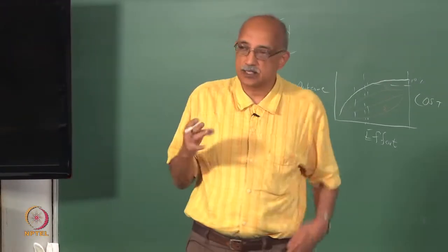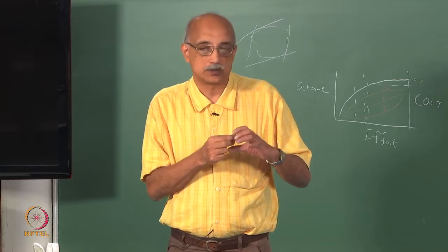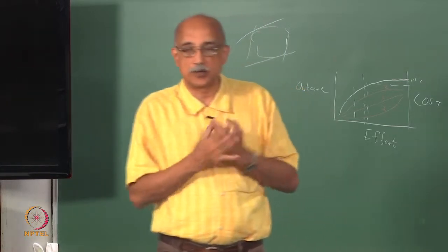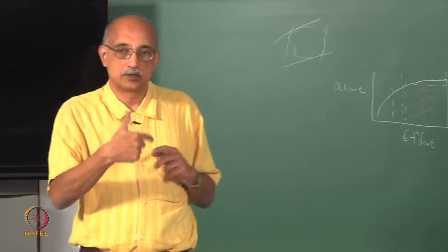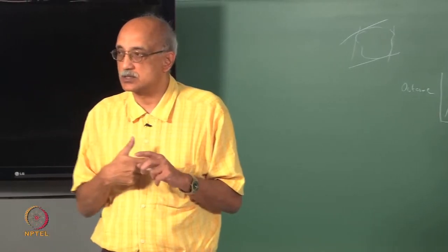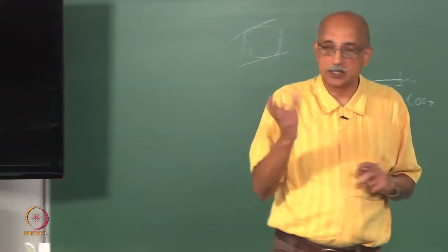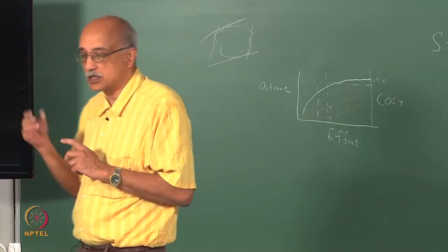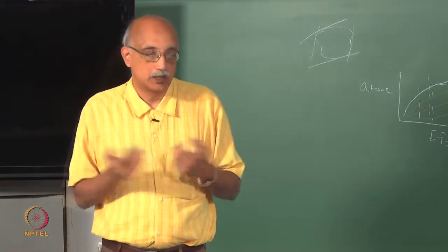For example, you can say that if it is a perfectly spherical particle, my intercept length would be the diameter, right. Whereas if you have a non-spherical particle, then the length of my intercept will be different for different angles of incidence, and I can then represent the bulkiness of the particle by the ratio between the intercept of the real particle versus the intercept for a spherical particle.